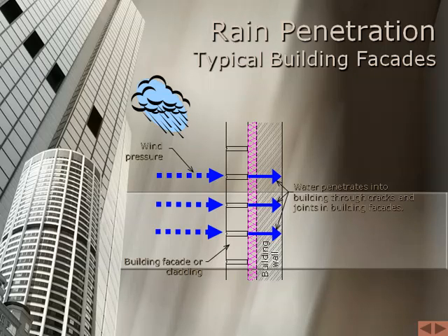For the face seal approach, very small pores and cracks may be covered with impermeable or semi-impermeable coatings, but these treatments are less likely to be effective for larger pores and cracks for a long period of time. Joints between components and materials can be sealed with gaskets or sealants. If these sealants are located where they are in contact with water, the seal must be perfect to be effective. This is often difficult to achieve because of fabrication, project site inaccuracies, or loose tolerances.